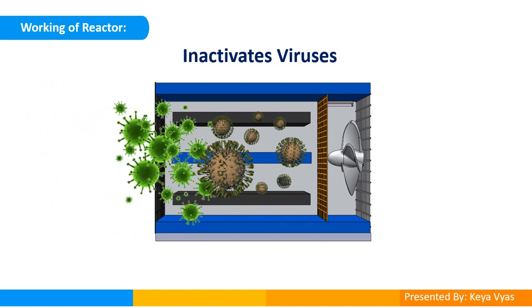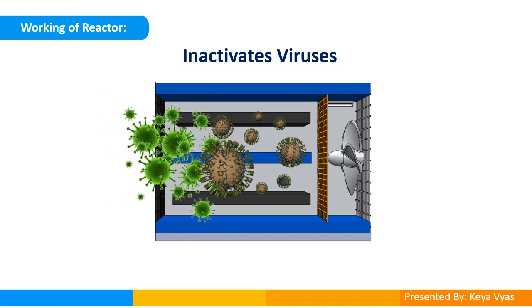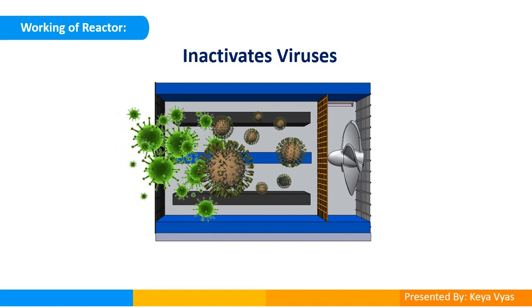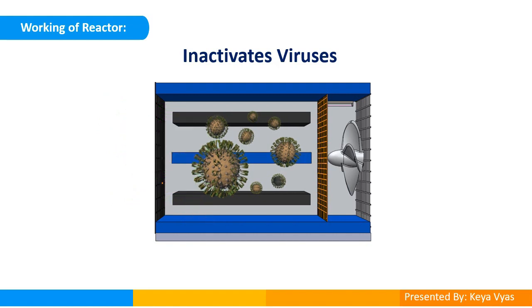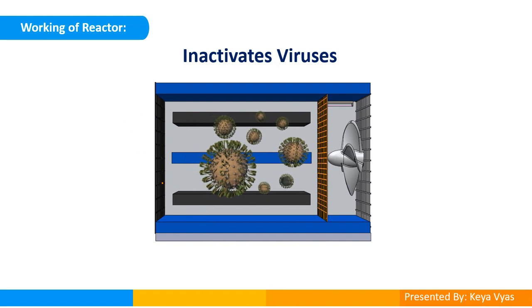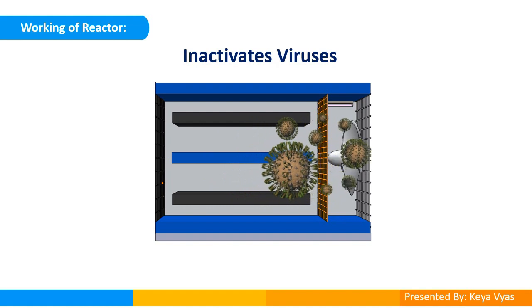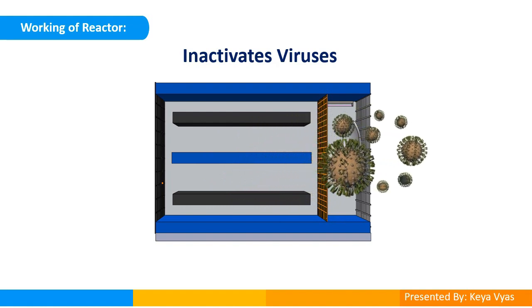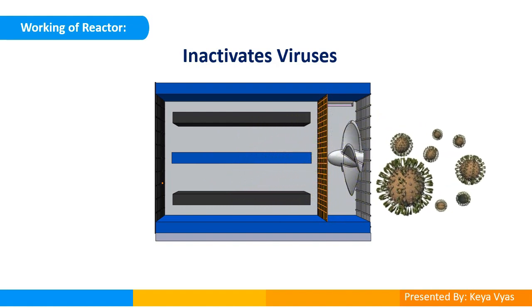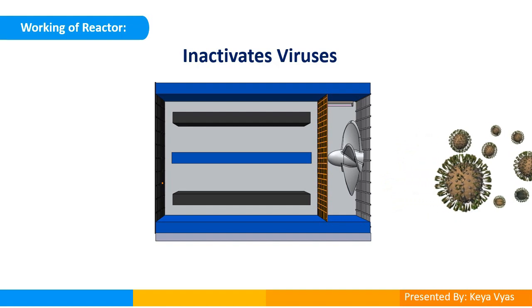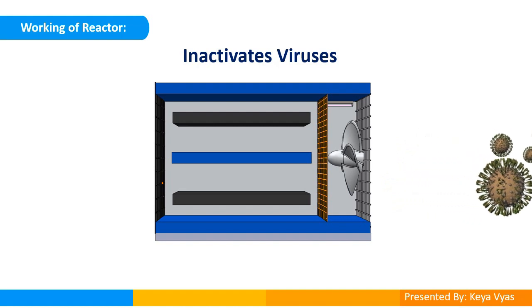Ozone is generated during this process, which should not be leaked out. So for that I have installed a UV lamp, that is a mercury lamp, which can degrade the ozone and prevent it from leaking out. HEPA filters are used at the end, so if any large particles remain they can be trapped. Efficiency can be increased by increasing the surface area of the electrodes, by increasing only length and width. This configuration is easy to construct and more compact than cylindrical devices.